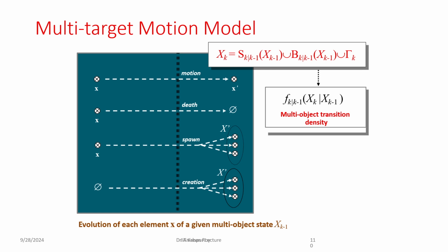Now, I will explain what is called my target model, in a little bit more depth. The target model is actually of 3 parts. One is the typical simple scenario 1. You have a target, your sensor picks the target, it gives you one measurement. Good, I am happy, simplest case. Scenario 2: you have a target, but no measurement is coming. Either the target could be out of the field of view of the sensor, or the target could be dead for a long time. That means you have a null set created.